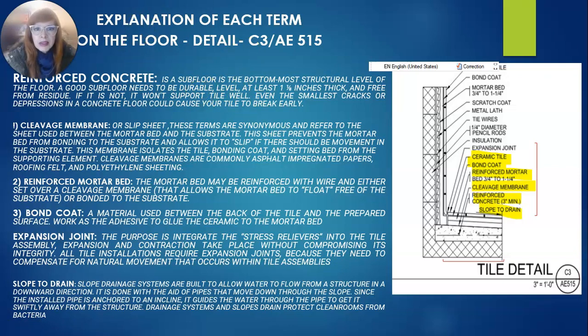Even the smallest cracks or depressions in a concrete floor could cause the tile to break early. It means that this reinforced concrete needs to be free of residue, very strong, because any depressions in a concrete could cause the tile to break.